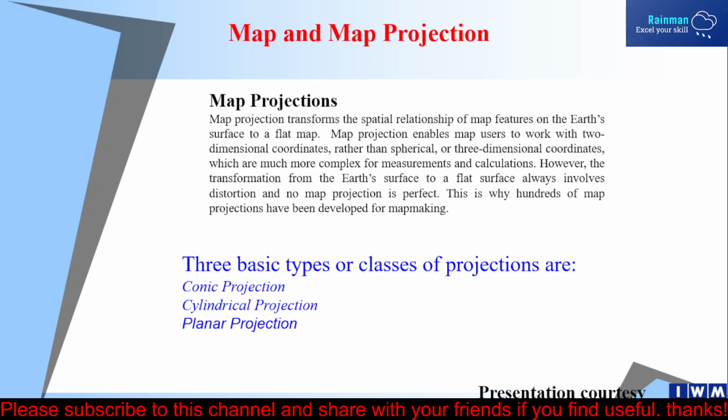A latitude longitude coordinate system is also used in some cases. Another one widely used all over the world is the UTM coordinate system. Bangladesh is actually located in UTM 45 north and 46 north zones. So these four coordinate systems are the most popular in Bangladesh. We Bangladeshi engineers are used to this type of projection system.